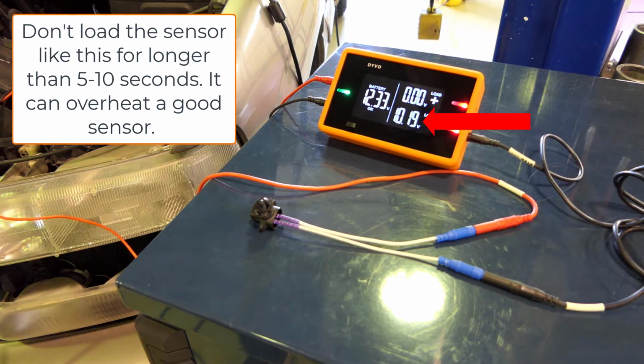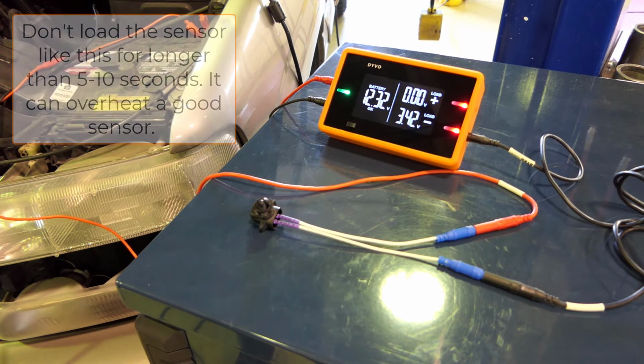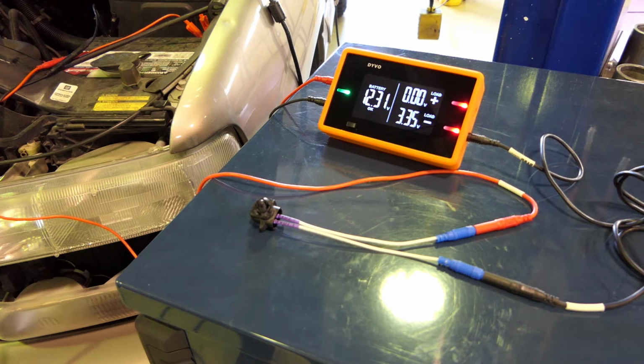This tells me this thermistor, this temperature sensor, is defective. Right away, I know this is defective. Look at how it just keeps dropping and dropping like that. What we're doing is applying a voltage and passing a current through here, and this temperature sensor is defective because that internal resistance is actually shorted. Right? It's maybe not a full dead short, but it's definitely a much lower resistance than what it should have, because of how quickly that value drops.